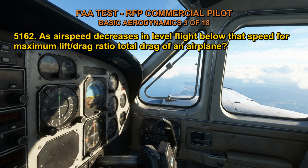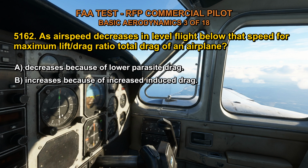Q5162. As airspeed decreases in level flight below that speed for maximum lift/drag ratio, total drag of an airplane. A. Decreases because of lower parasite drag. B. Increases because of increased induced drag. C. Increases because of increased parasite drag.